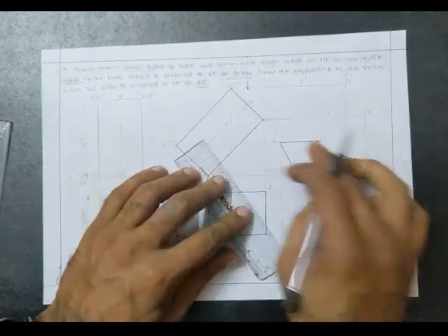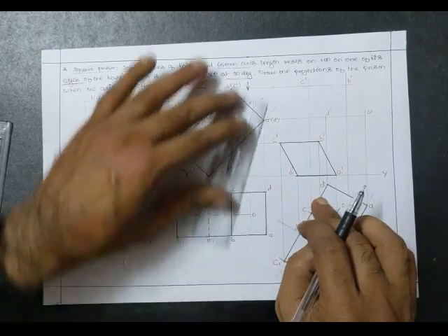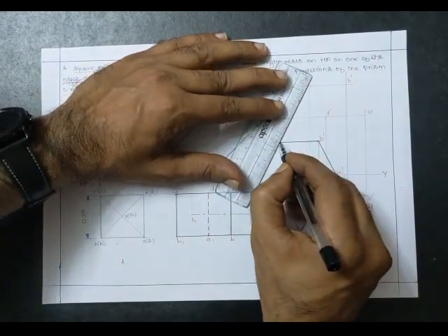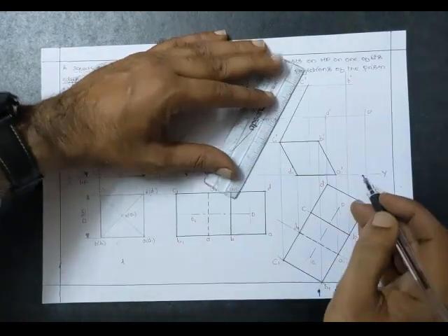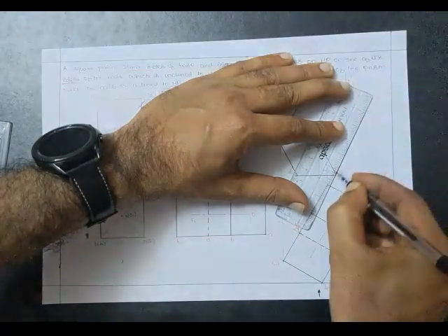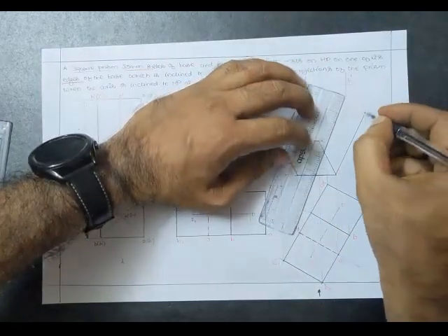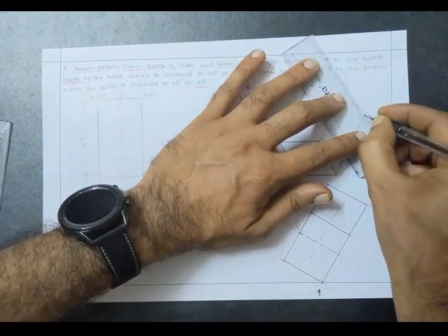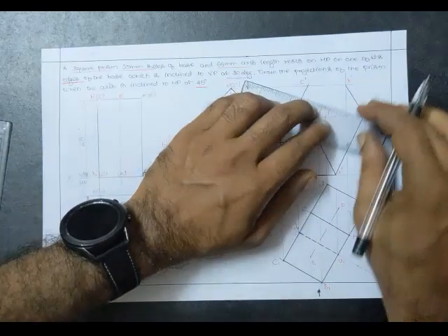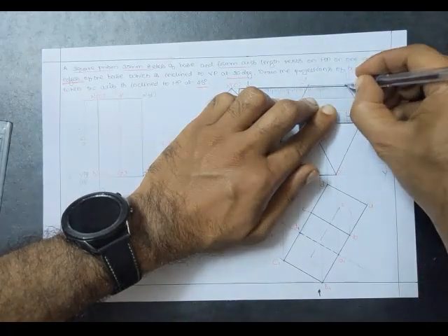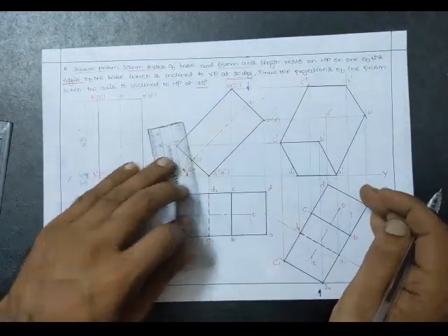So once you've done that, look at this particular rectangle and check which is the outermost part of this one. So it is C. So I'm going to draw parallel lines. That is, I'm just connecting the boundary. This is the simplest way to get the boundary. After getting the visible face or visible base, it is very easy to check with the outermost corners, and from that you can complete the outermost boundary of a solid.